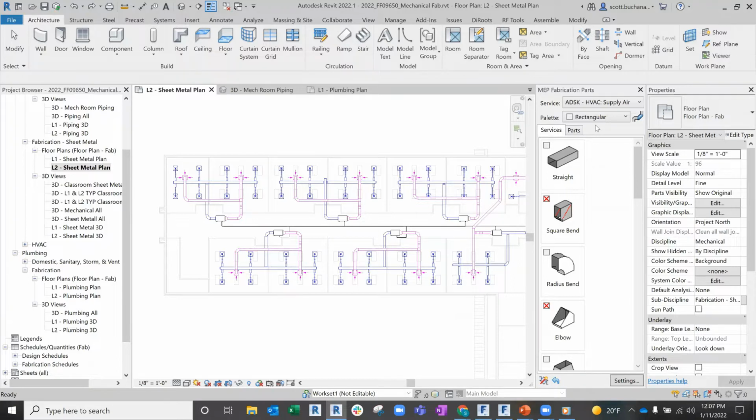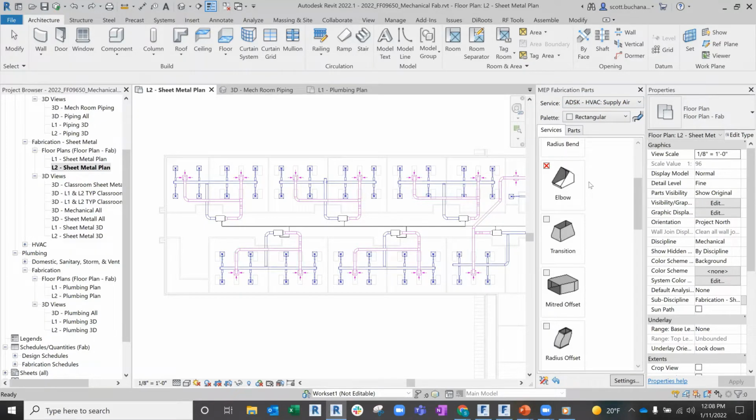No, even though it's called a database, it's just a giant configuration. It's a group of settings that are defining, hey, in my shop, if I'm going to do supply air, positive 2-inch, 4-inch, whatever, these are the types of fittings we use. We use slip and drive connectors up to this size. We use TDCs up to another size. And so you get to build out that shop standard inside of there.